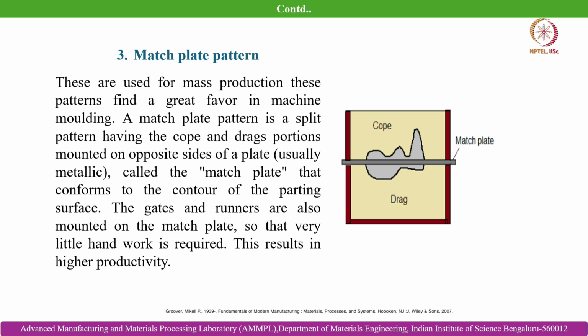This is also useful for patterns which need support, and for objects which have complicated contours and thin sections, where effective removal of the pattern becomes difficult. Also, because of the thin sections and fragile pattern material, the pattern can fail during sand ramming on top of it. Those instances can be saved by using the match plate pattern.